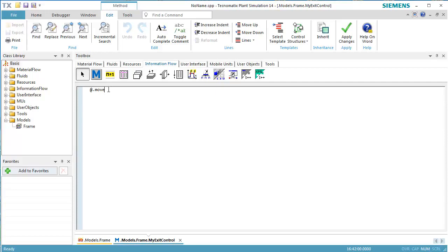The source produces 1,000 parts and moves these to the station. We are going to count the number of incoming parts and then, after a certain number has been reached, move the following parts onto a different successor. To do so, we'll read the statistics value stat_num_in. First, we delete the line which was automatically created. We then declare a local variable.